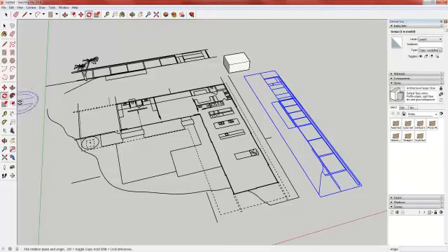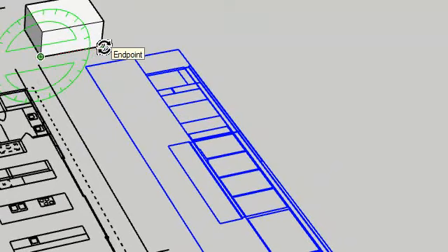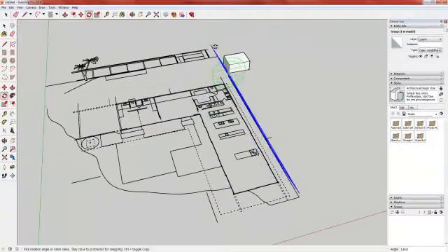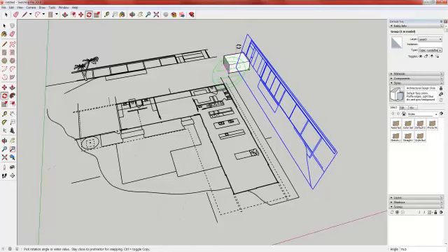I'm going to click the rotation tool, and notice as I hover around my box, if I'm flat, I'm on the blue axis, rotating in the Z direction. Here I'm rotating around the green axis, and here I would be rotating around the red axis. So I'm going to hover on the green axis, and we're not picky about where our base is. I'm going to left click at the bottom of the base, and then left click again to set my base rotation, just like traditional rotation. Now as I rotate, you can see I'm rotating the section vertically. I'm going to move my cursor generally in the direction, then type in 90 and hit enter.